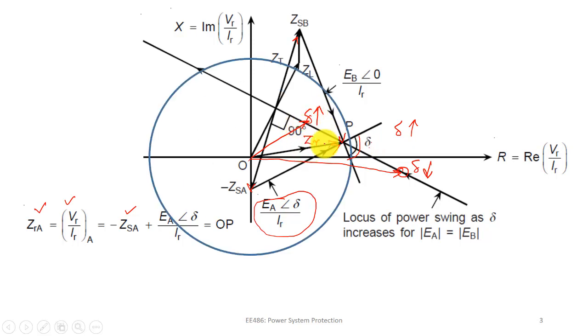We can see this curve. This is your operating characteristic of the impedance relay, right? Under this operating characteristic, under this circle, whichever point ZR lies, that will give us the trip signal, and outside it will give us the restraining signal.